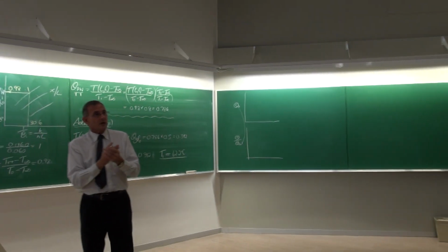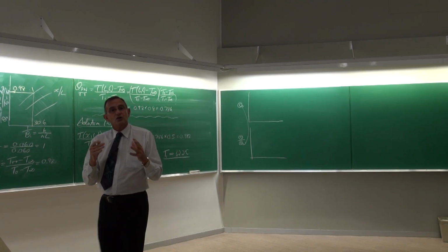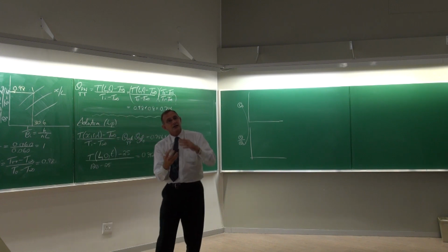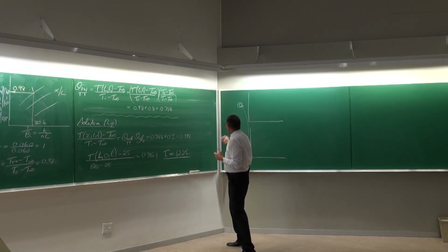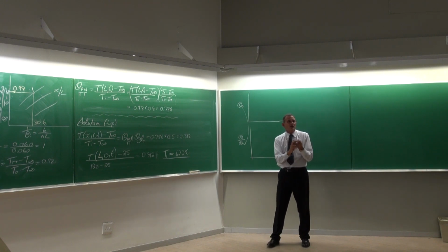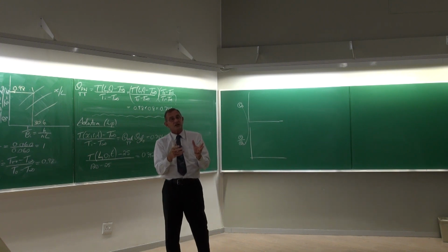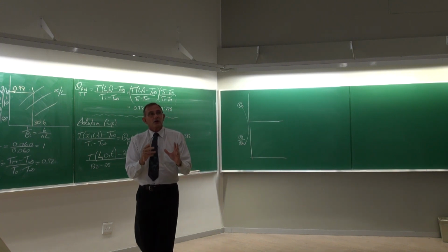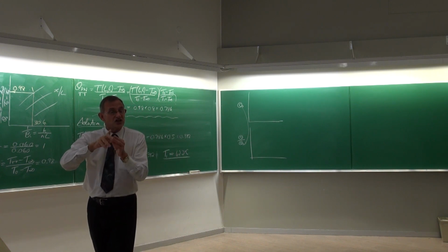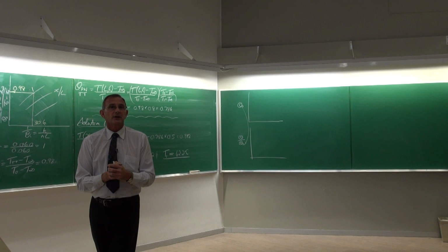With the equations, just coming back to them, remember the first set of simplifications would typically be where x is equal to 0 and r is equal to 0. They give a set of equations which are all for the center, where the non-dimensionalized time is larger than 0.2. So that's the simplest set of equations. The next set of equations is for when it is not on the center line. Then you need to take into consideration an extra cosine term or the Bessel function term. Okay.